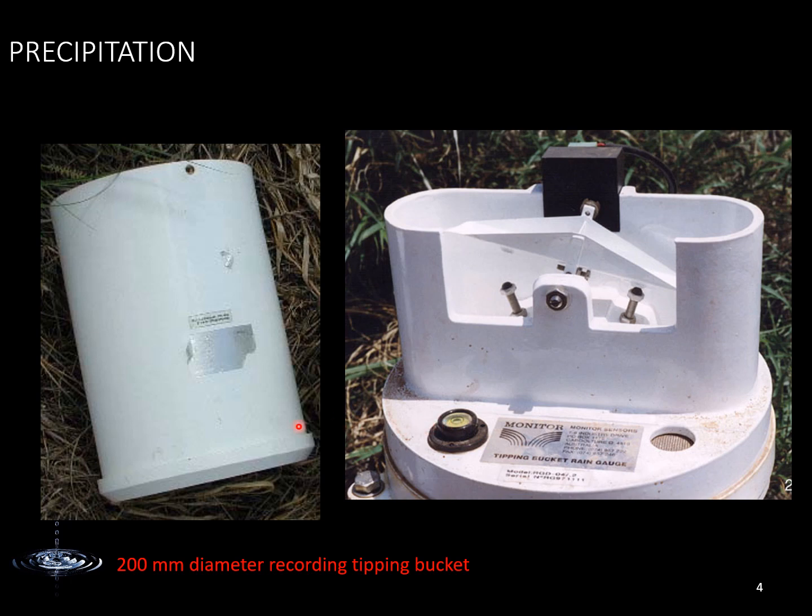This is an example of a tipping bucket. Okay, so when we measure the precipitation, this is at the top, so this part goes here, right? And then we know the area of this bucket. And what happens is when the rainfall occurs, it falls inside this bucket and then eventually starts to drop at the bucket here. So you can see here there are two buckets. The first bucket is on the left hand side and the second one is on the right hand side.